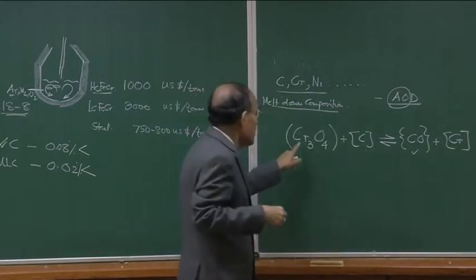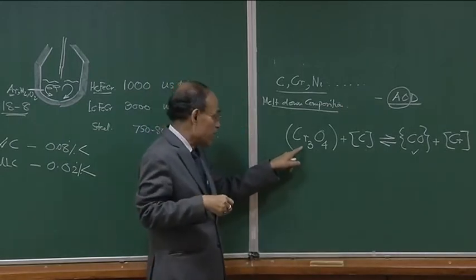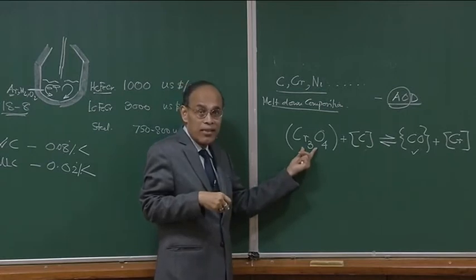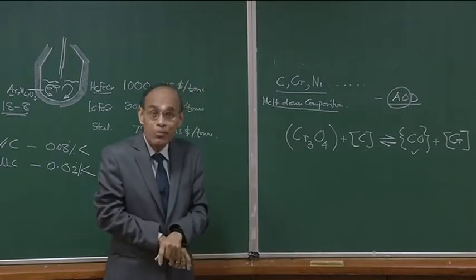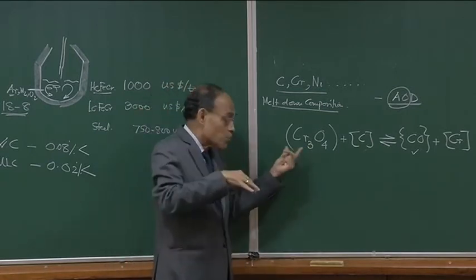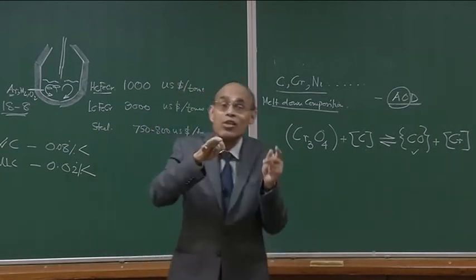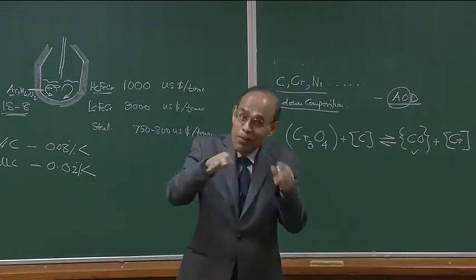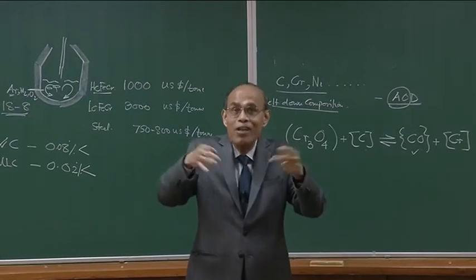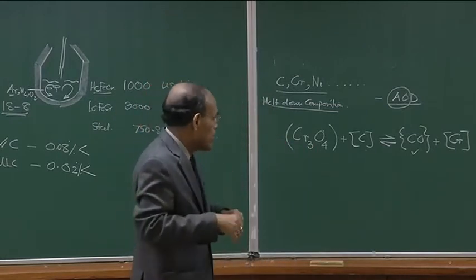On the other hand, if the activity coefficient is extremely high, in that case we can expect that the species has a great tendency to leave; it is not very comfortable in the slag, it is not very stable in the slag. So, it is looking for an avenue to go out of the slag phase itself.